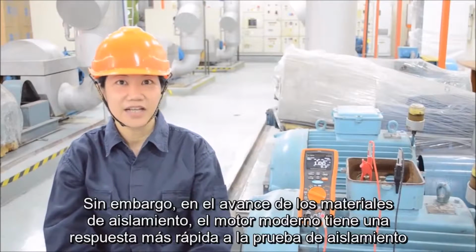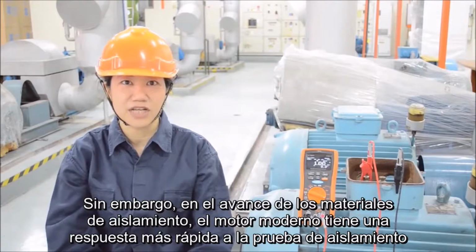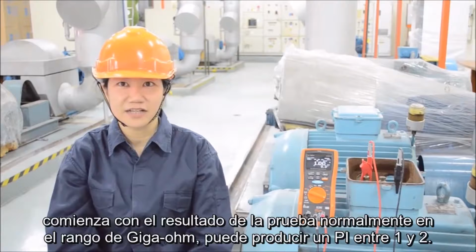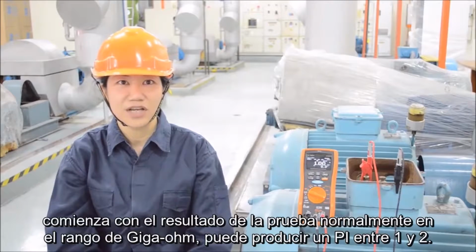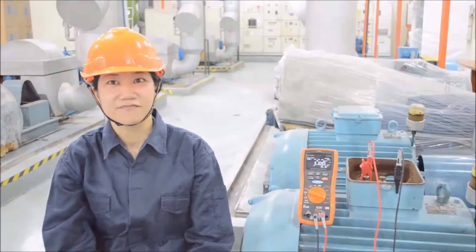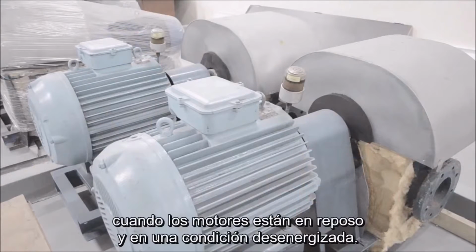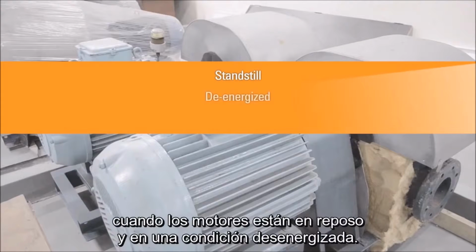However, with the advance of insulation materials, the modern motor has a faster response to the insulation test. Starting with test results normally in the gigaohm range, it may yield a PI between 1 and 2. In this case, the PI calculation may be disregarded. As always, for effective testing and safety, the insulation test should only be performed when the motors are at standstill and in a de-energized condition.